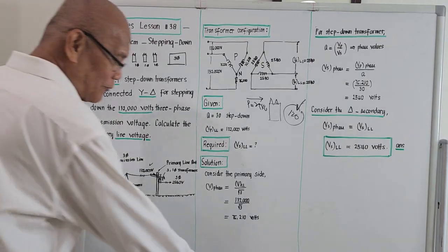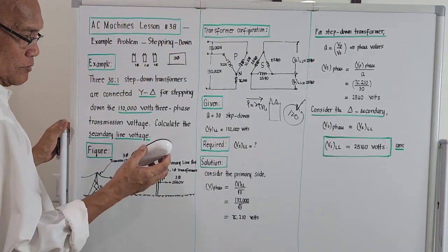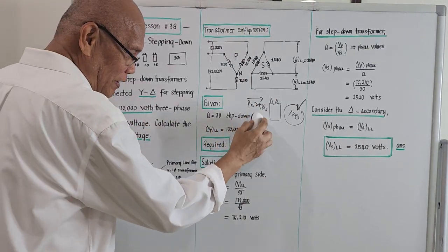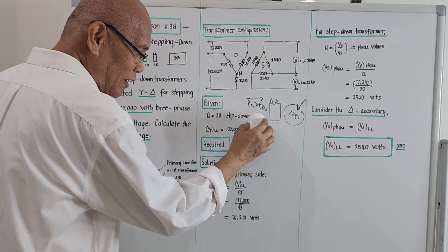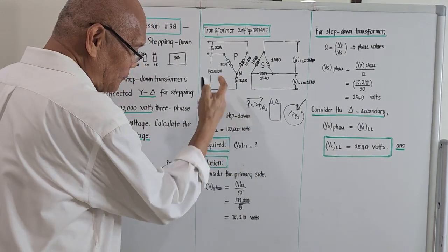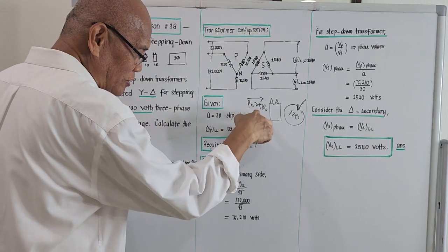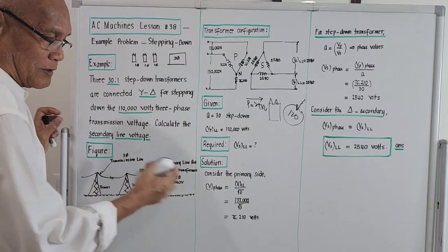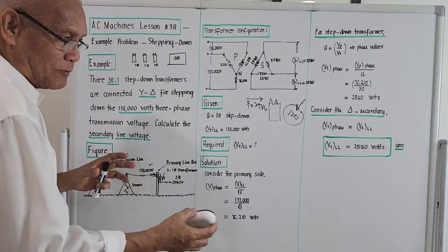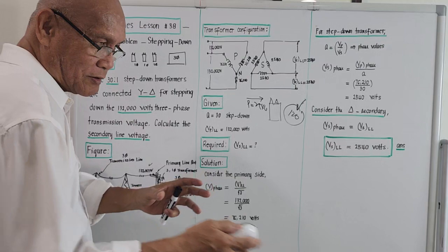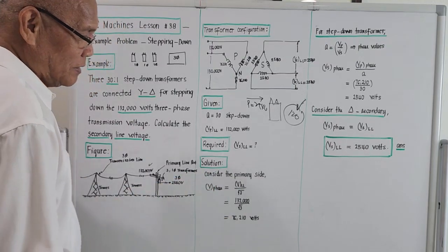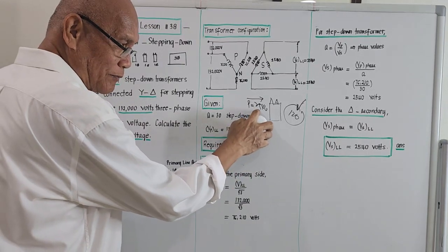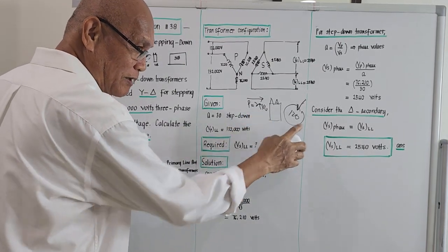Also, I am just giving you a preview on how we are doing the stepping down for the voltage of the primary of the distribution transformer to be a lower value. Because if you put this 132,000 here, there's a problem. So actually, we are stepping down the voltage to a certain value, which is safe to the electricians and the house customers. So upon reaching the secondary post, the primary input voltage now will be 2540 and the output will be 120 if you are in the USA.